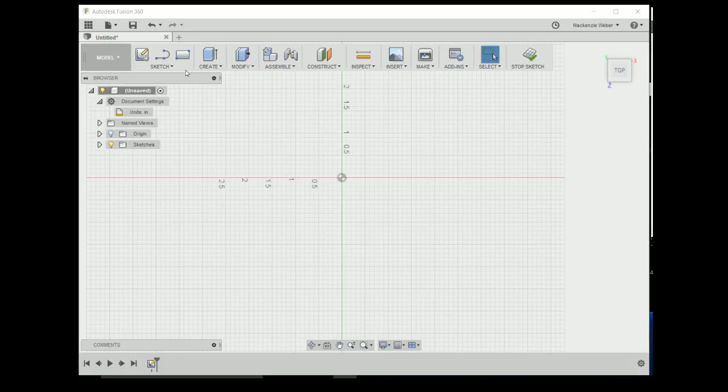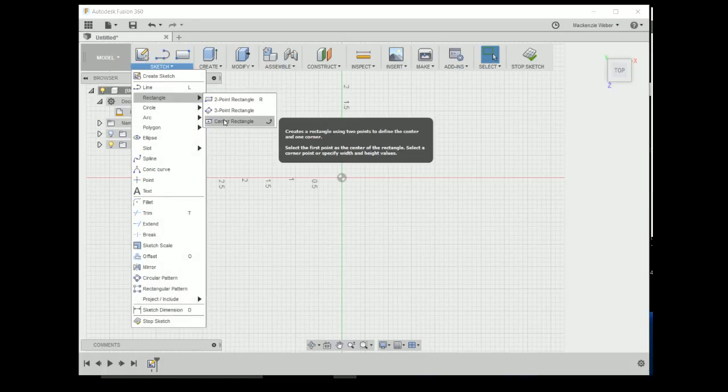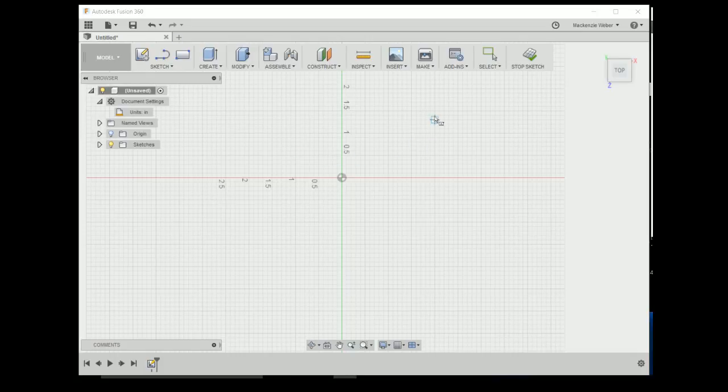So for example, if we wanted to make a tabletop, just to keep it simple right now, a rectangular tabletop, we can go into Sketch Tools, we can select Center Rectangle, and that will allow us to draw a rectangle starting with the center. And we can click here at the origin, because that's just an easy point to start for the center of the rectangle.